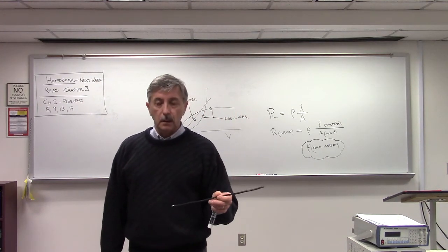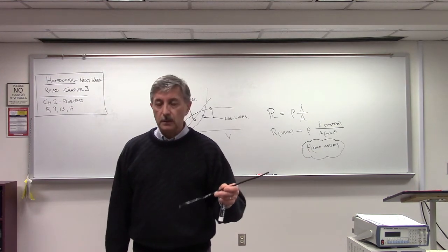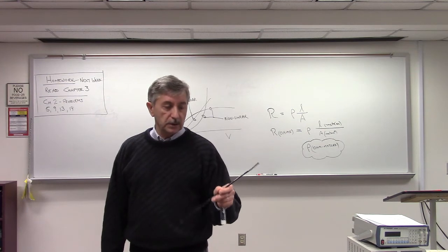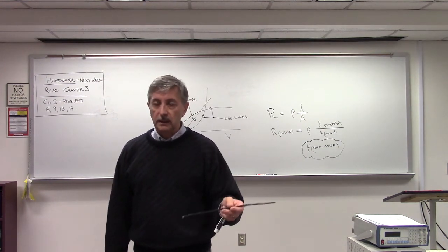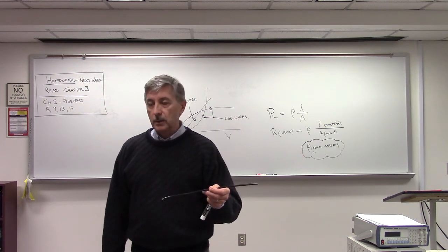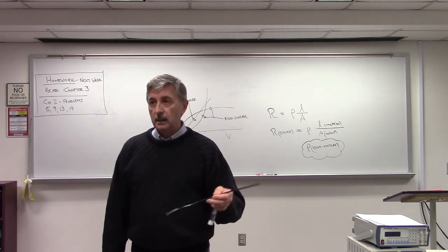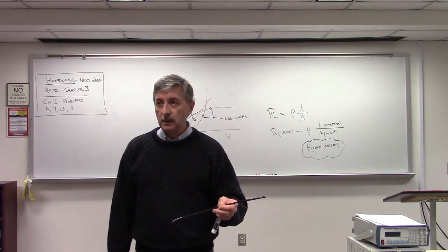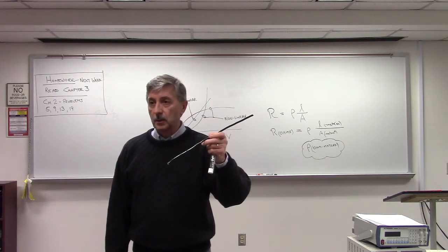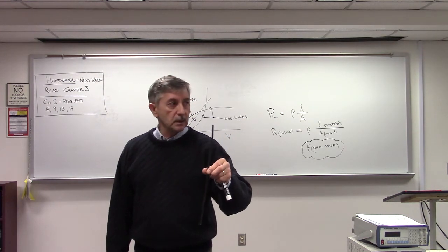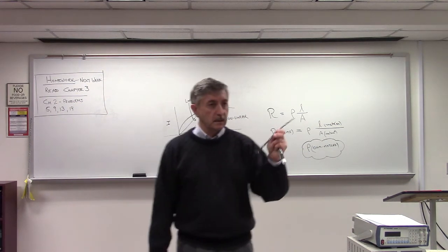number of a wire is in terms of its American wire gauge, AWG, and the higher the number, it's kind of a reverse relationship. The higher the number, the smaller the wire. So telephone wire is like 24 AWG. House wire is 12, so it's a little bit bigger. This is number 6 wire, so this is good for like 50 amps. That's number 6.